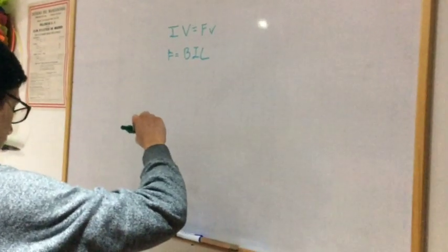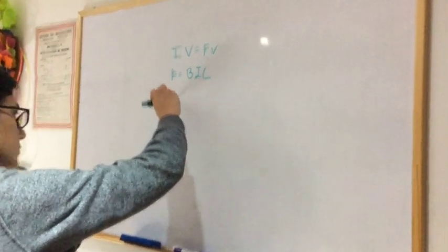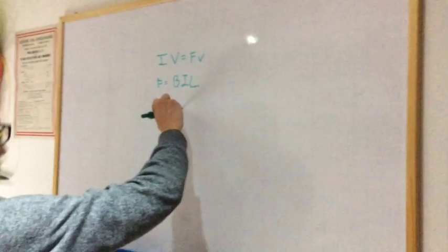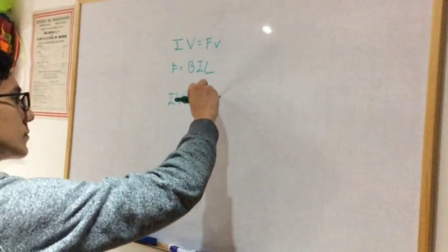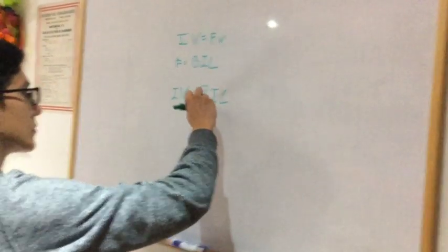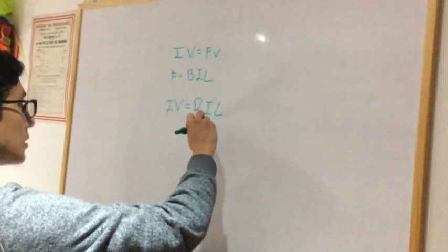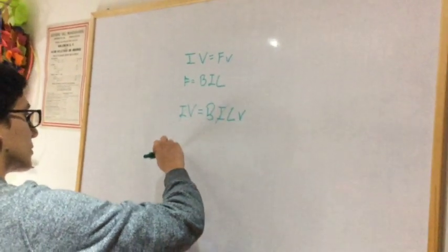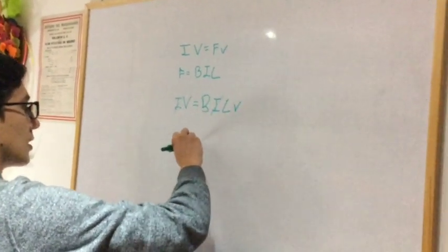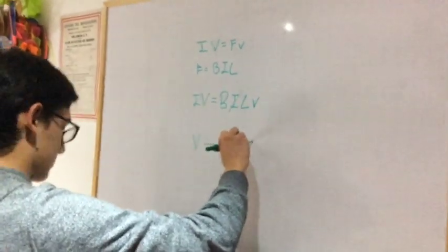From here we could derive the following formula for potential difference. As the power induced is equal to the power required, we say that current times potential difference is equal to force times speed. Replacing the force, which is equal to magnetic field strength times current times length, into the other formula will give us the EMF to be equal to magnetic field strength times speed times length.